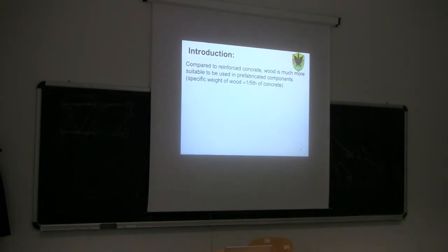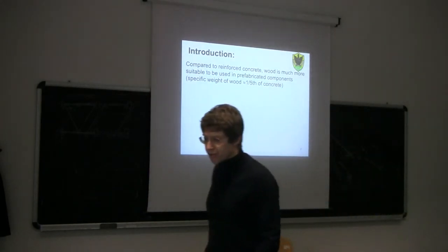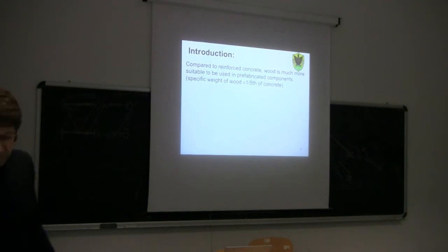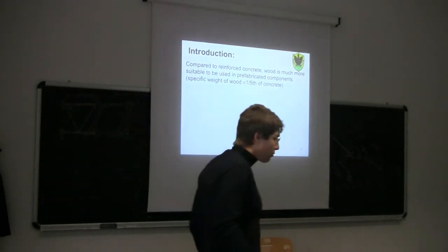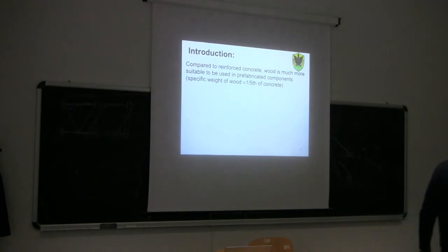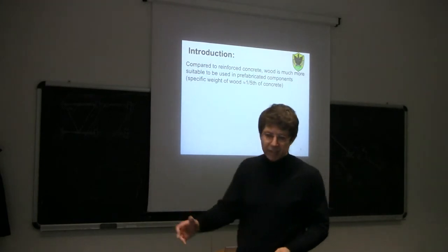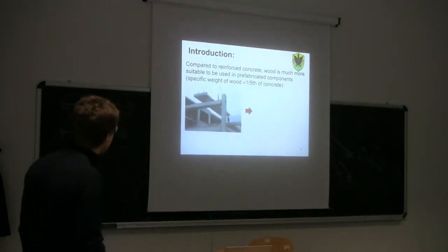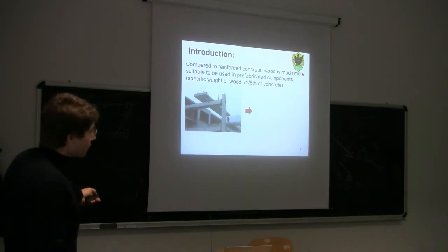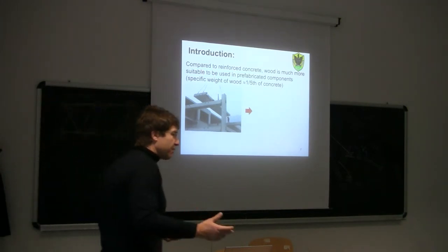Of course, you can also have some fully prefabricated solution with reinforced concrete. Think about, for example, industrial solutions, for example, for warehouses or for a multi-story garage. In this case, you have the whole columns and the whole panel made of prefabricated reinforced concrete. Usually they are pre-stressed, and then the different members are delivered to the building site and connected together. However, full prefabrication in reinforced concrete is not very common.